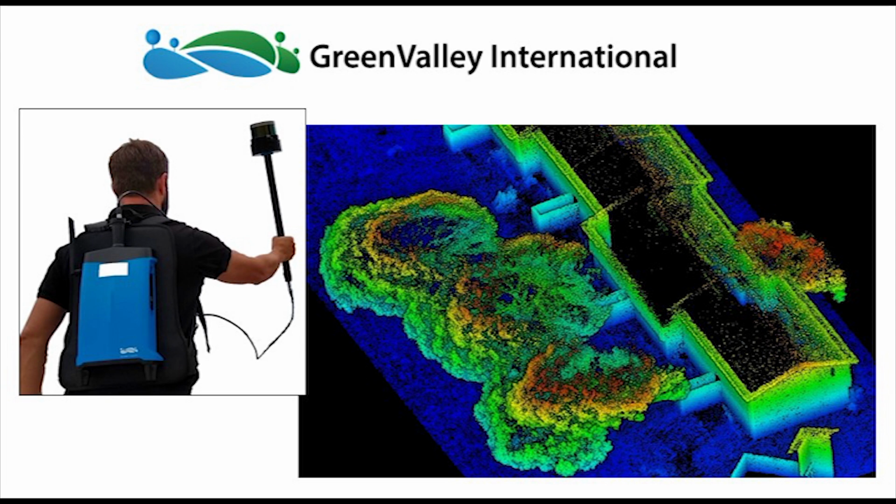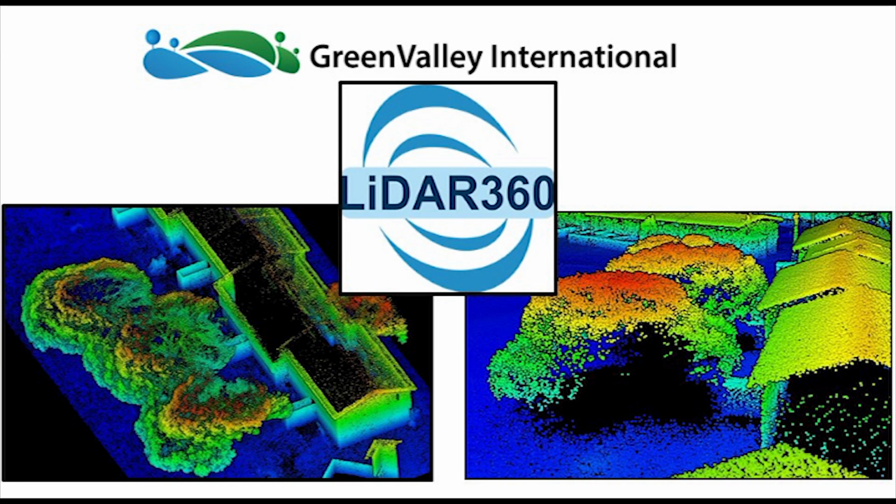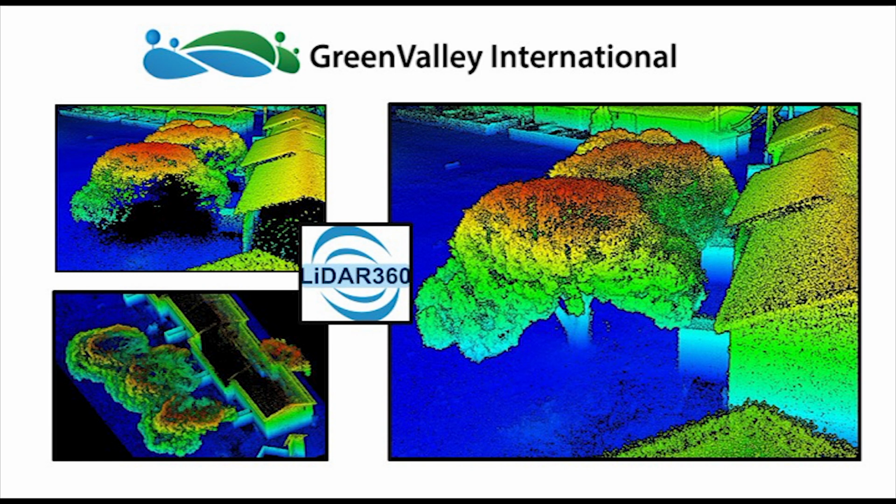So I had this idea to use LiDAR 360 and a tool in it called the rectify tool to align the two data sets and thereby remove the data holes found in each of the separate data sets. I then merged these two data sets to create a single point cloud that was spatially coherent in the sense that all objects almost had full coverage of LiDAR data.